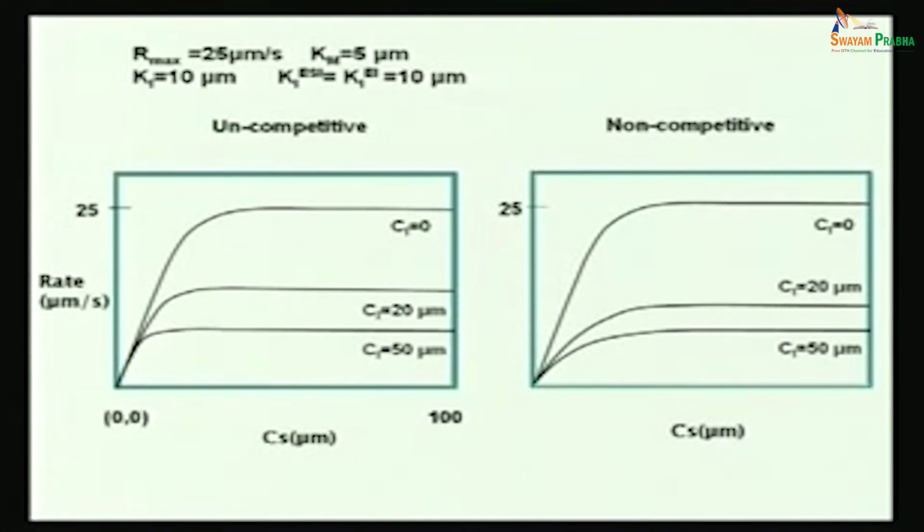So what would be the other mechanisms? One of the ways, of course, is to keep the volume the same but increase the input-output rates, for a steady-state CSTR, so that the residence time is decreased. That's one of the possibilities. But what could be other possibilities? We can reduce the rate of formation of product. Then how will you reduce that? By varying the flow rate. No, flow rate we already said, that's a possibility, that you can increase the flow rate, as a result of which you can decrease the residence time. That's one possibility. What are other possibilities?